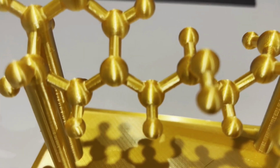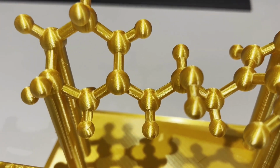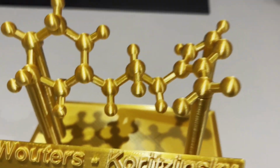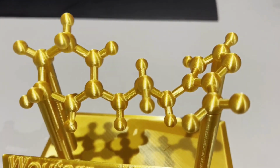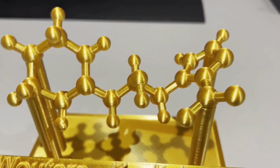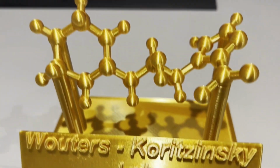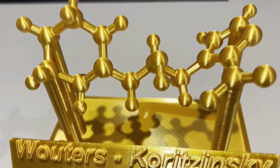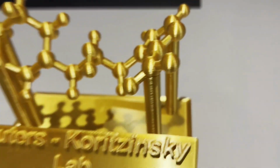And with a model like this, even with basically 100% infill density in the balls and in the sticks themselves, these are relatively fragile. So when I was removing the supports, I basically had to use these pliers to remove just the support right below the ball, rather than trying to remove the entire support all in one go, or else there's a good chance that either the bonds would break, the balls would break, or these manual supports would break.